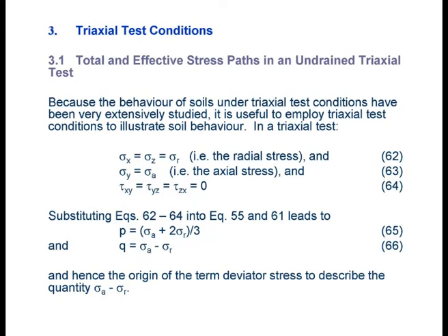Okay, we now go to a triaxial test. Why is it a triaxial test? Because as I mentioned to you, in a triaxial test, it turns out that the definition of P and Q becomes very, very simple. What is the condition of a triaxial test? The triaxial test is axisymmetric, a circular specimen, right? Circular specimen.